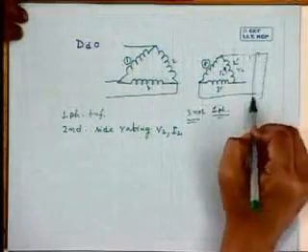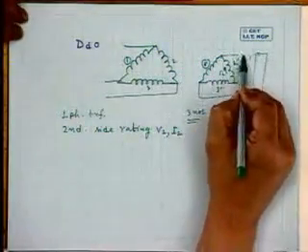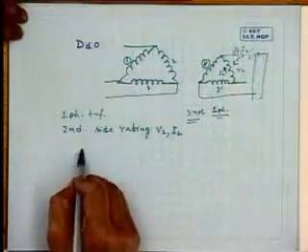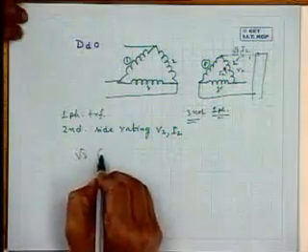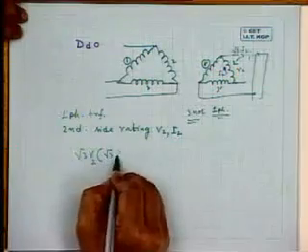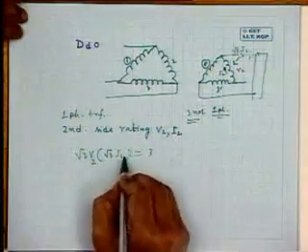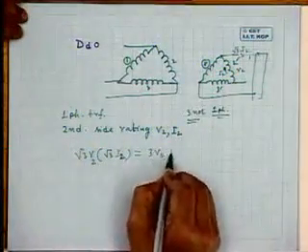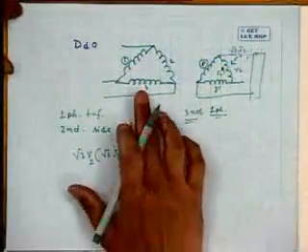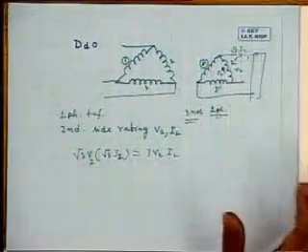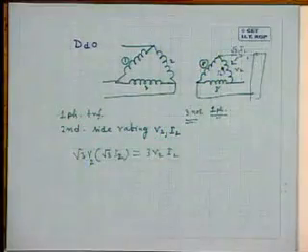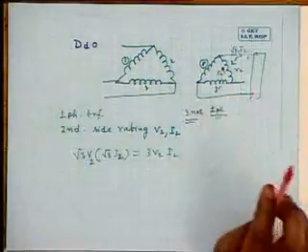Now, when all the 3 transformers are present, how much kVA can you deliver? Rated current is I2, you can allow root 3 I2 to flow. So, total kVA that can be handled by this is root 3 into V into the line current, root 3 IL, that is 3 V2 into I2. That is the total kVA rating you can supply. This is understood. That is, each one is 10 kVA, 20 kVA I can supply, 30 kVA I can supply.